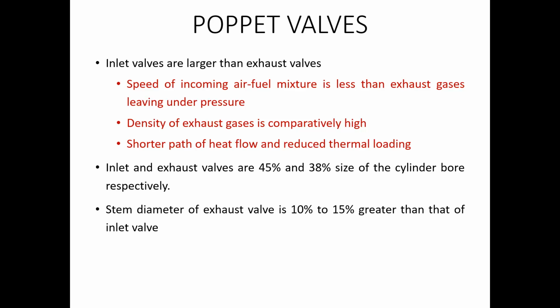The second reason is that the exhaust valves are more associated with high temperature, because usually the hot gases leave through the exhaust valve, and there is always a chance that the exhaust valves remain at a very hot condition compared with the inlet valves.